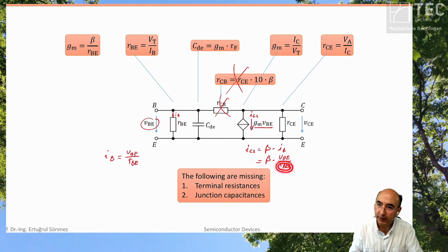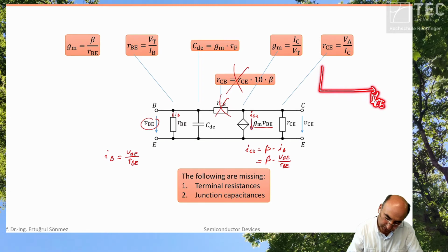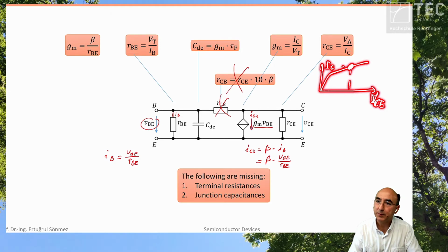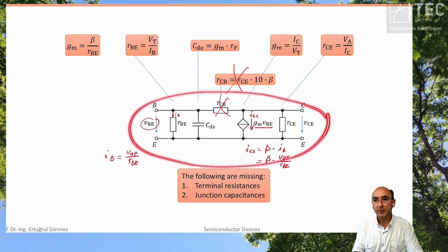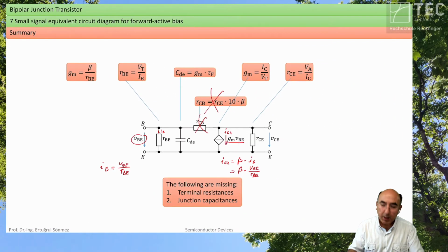You can also take this equation. And RCE, you have to remember on your imaginary eye, VCE as a function of IC, and it's this slope in an operating point, in a bias point. So if you take this small signal equivalent circuit, you should remember backwards how you calculate this. Let's put all the slides into this slide, which is relevant, okay?